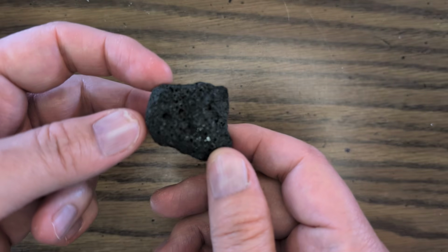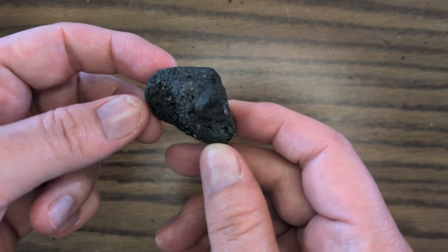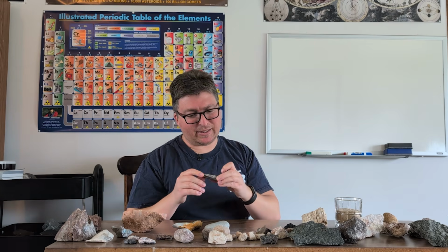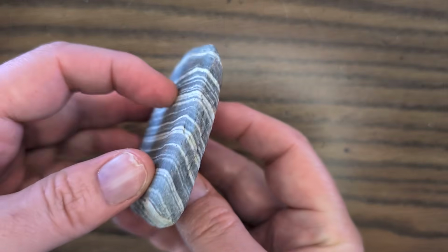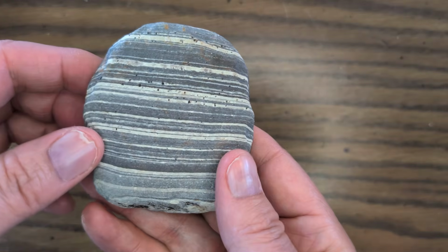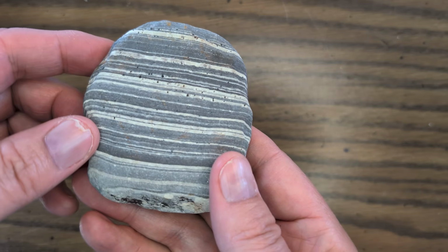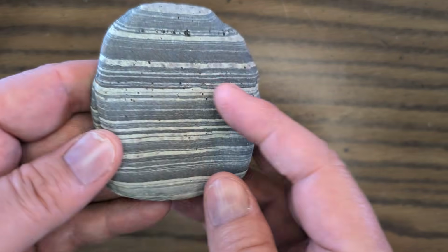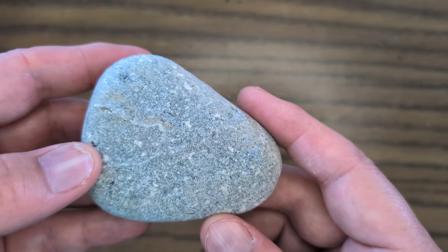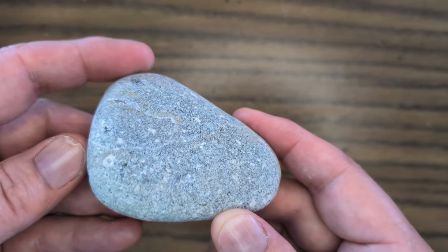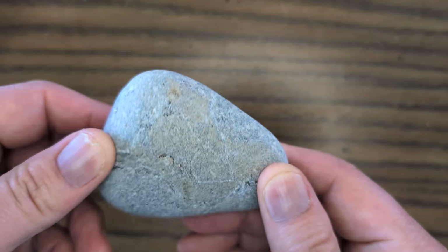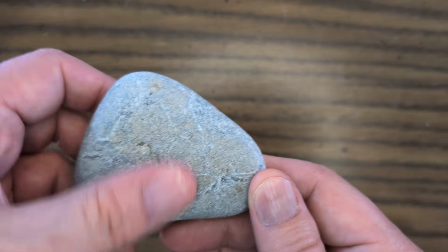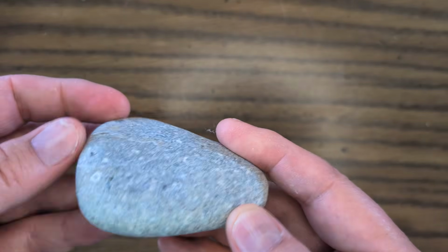But those pore spaces are much better connected, and so it's a much more permeable rock. Sandstone tends to have higher permeability and porosity than most rocks, but it has a lot less than the unconsolidated sand because those sand grains have all been mineralized together now. And once you start getting to more dense rocks like limestone and chert and your granite, you're going to have very low porosity and very low permeability unless there are a lot of fractures in the rock.